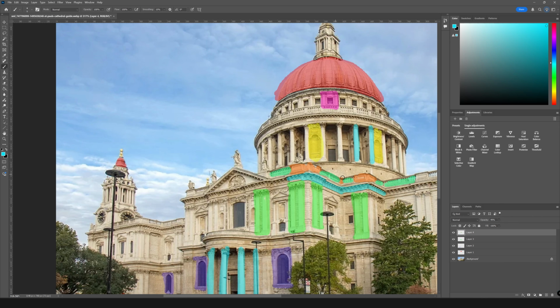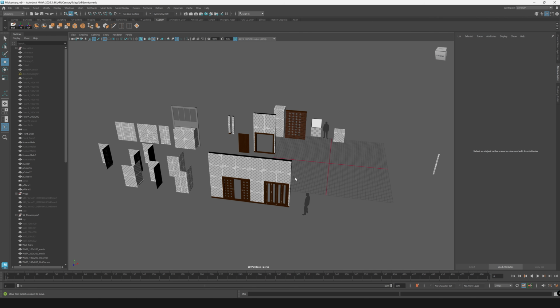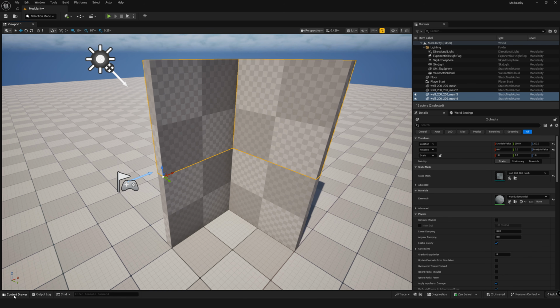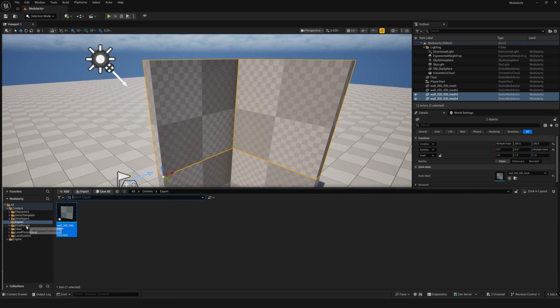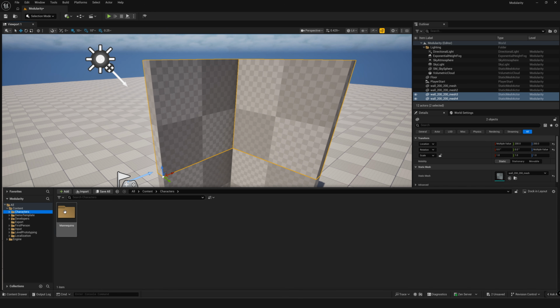You can also use tileables or your own baked assets. It's also a versatile thing as well. Just make sure you're using proper physical scale with a human scale reference. If you ever need a human scale reference character, you can always go into Unreal Engine and find either one of the, I believe, first person characters, or there's also a third person mannequin.